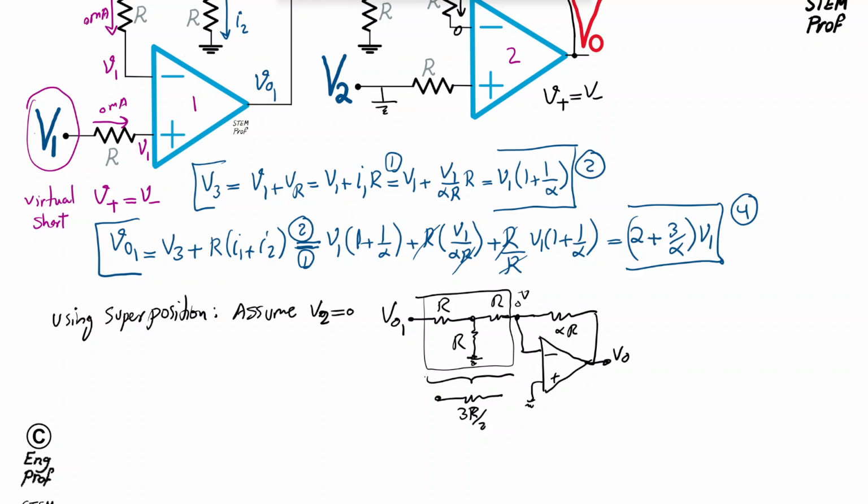Okay, this now looks very simple to calculate, because we can say the current that is injected into the circuit, and I'm going to use a different color so that it is clear, let's call it I3, because I have used I1 and I2 before. I3 is simply calculated like this: I3 is equal to Vout1 divided by 3R over 2. That's the resistance observed from Vout1 to ground.